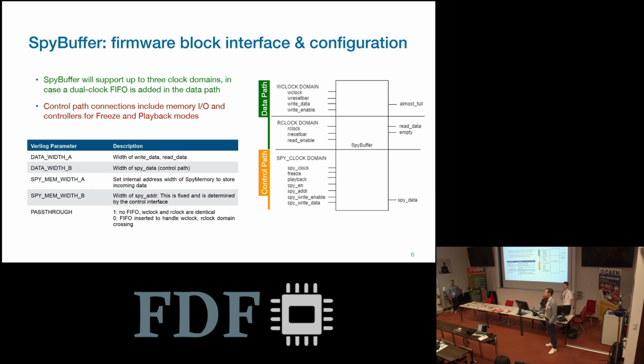No more questions? Just on this same topic, you just need to add an attribute to the element that is storing the information to define it. So it's an attribute in VHDL. And also, UltraRAM doesn't support two clocks, so I think it should be out of the equation for that. Yeah, maybe for this I have to double check. I'm sorry about that.